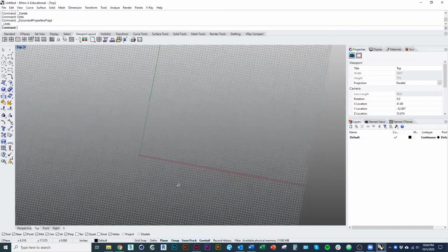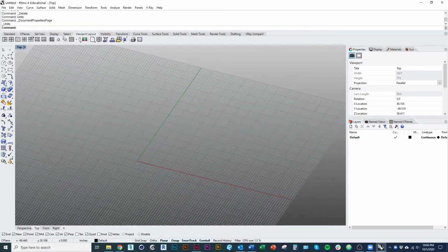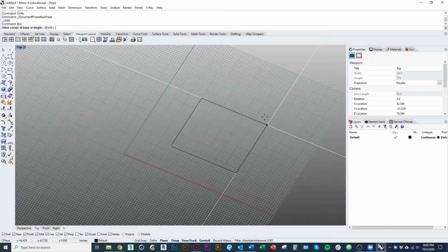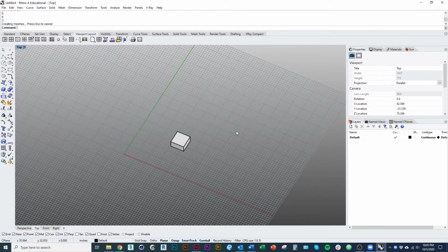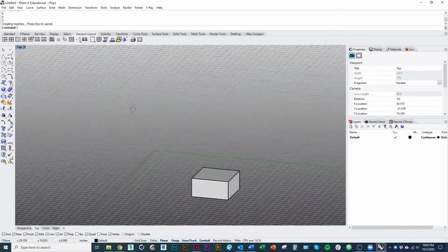So I'm going to just make a box. I'm going to do that using some of the solid modeling tools we have at our disposal, which are underneath the little box icon here. You can also get to the command by just typing in box in the command line. I can click anywhere to start drawing my box, and then I can type in dimensions, which are 6 by 6 by 3. And that's in inches. So there's kind of the volume now.